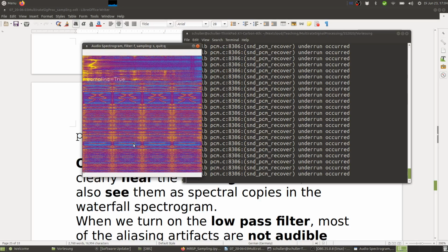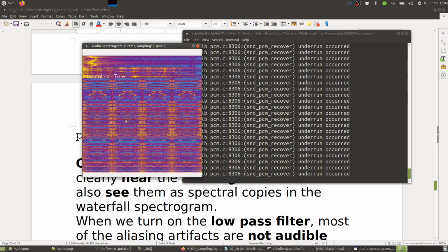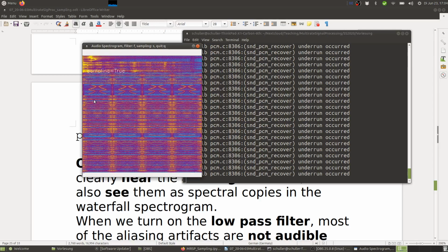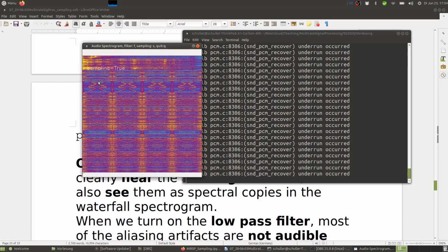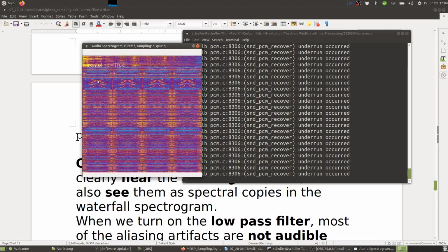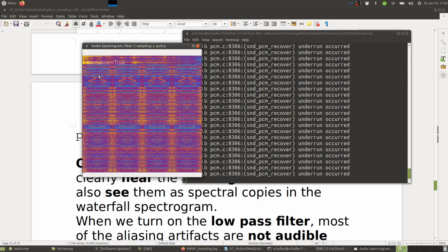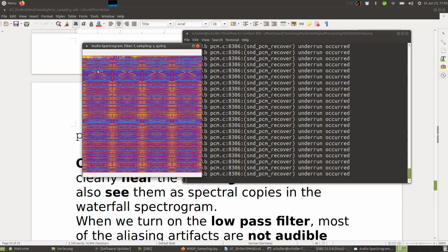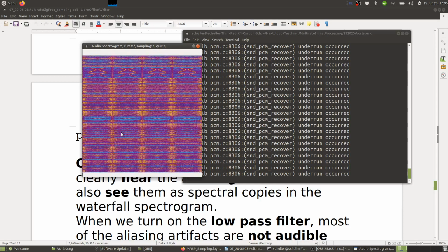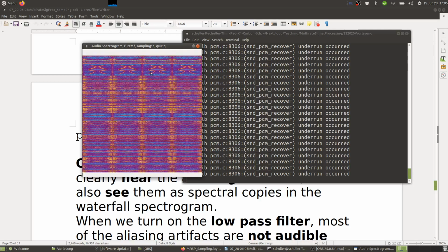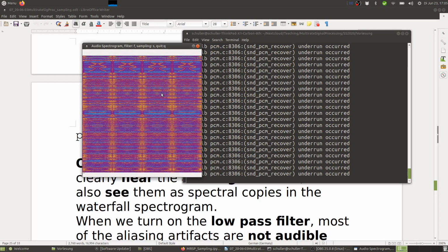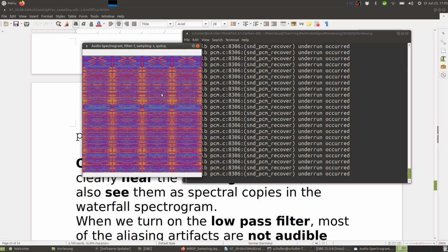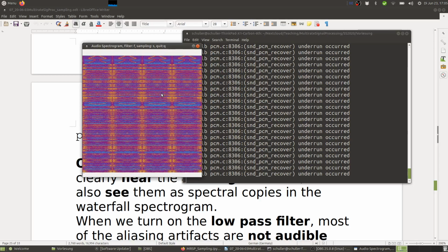So that's why it's important to limit the spectral range first, at the beginning, with the first low pass filter before sampling, to make sure that the spectral copies will not overlap. You can see here this is the original, and when I go up with the whistling they almost touch. So we have to make sure that they don't overlap, right? So that's why it's important to limit this frequency range at the input. And then after upsampling we have to make sure that we remove all those spectral copies before playback to avoid this chirpy ringing artifacts.